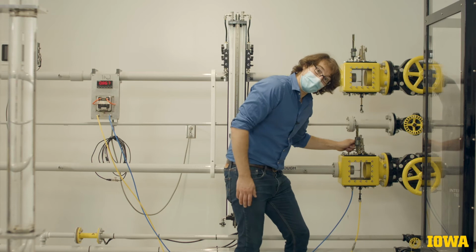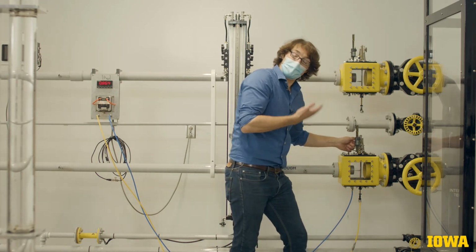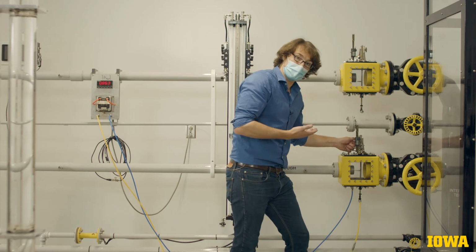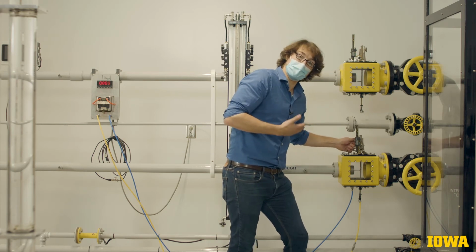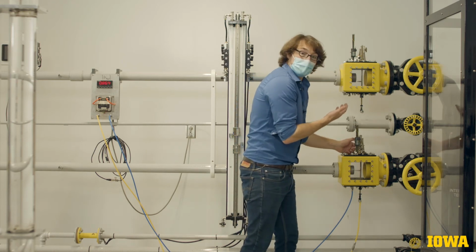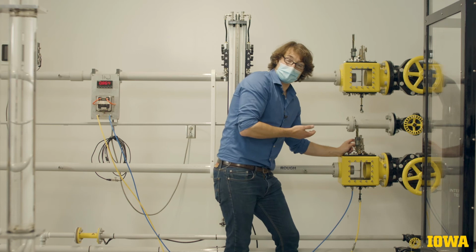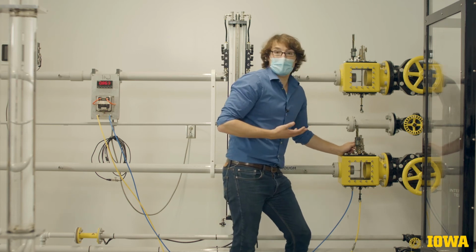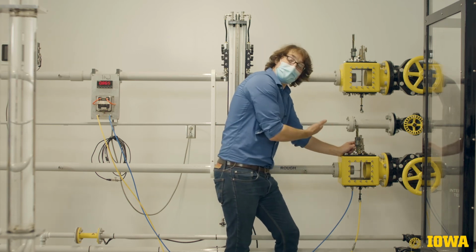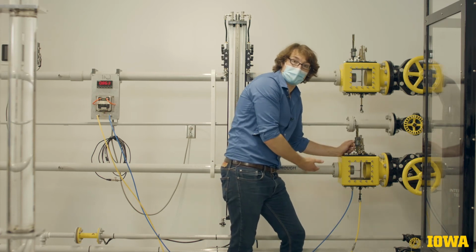As with the smooth pipe, we'll measure those at positions of 0, 5, 10, 15, 20, 23, and 24 millimeters from center line. We'll go ahead and do this both below and above the center line, which will allow us then to get a fully defined picture of what the velocity profile across the pipe's diameter looks like.